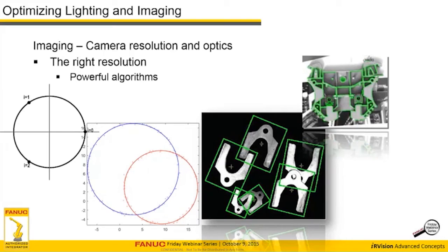And what happens is there are so many points that are discovered around the edge of that object that small errors introduced by lower resolution, small errors in the individual point, will not dramatically affect the absolute center or the absolute origin that's returned by the algorithm. And that's why for most location applications, going to the extent, the cost, the speed reduction, and so on of super high resolution imaging is not necessary.